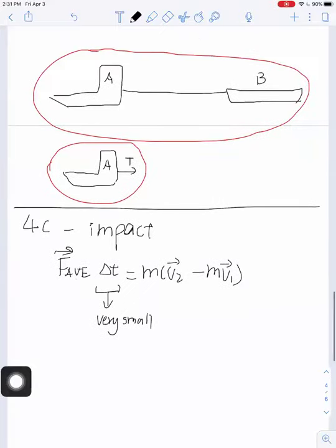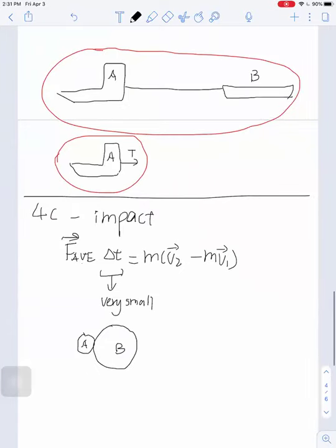And remember the impact problem example we did: we start with two particles, A and B, that impact each other. The first thing is you need to identify your t and n coordinates. So we have this line and this perpendicular line. This line here is t, the plane of contact, and the other line n is the line of impact.